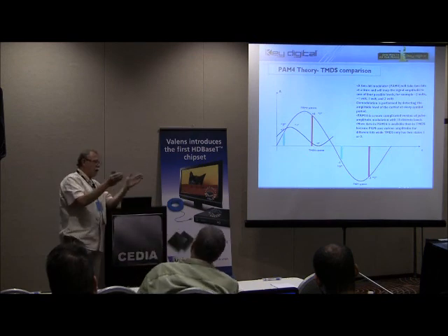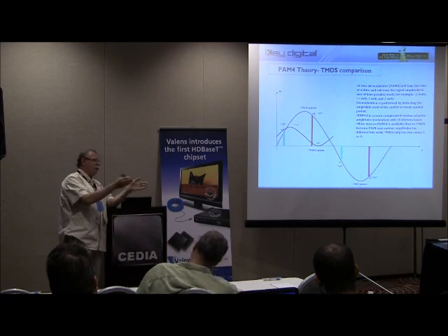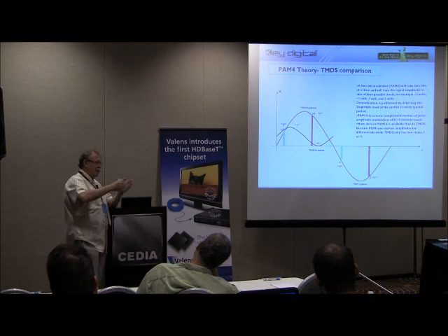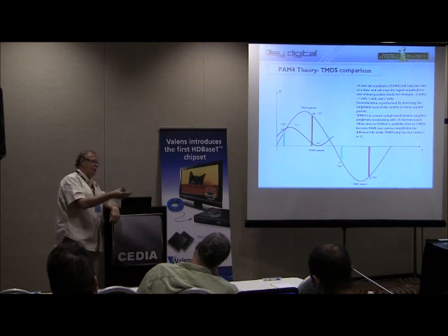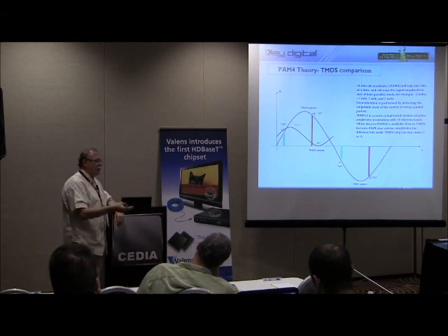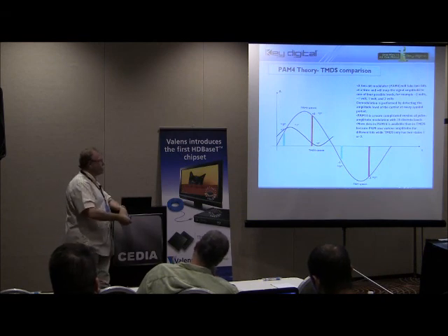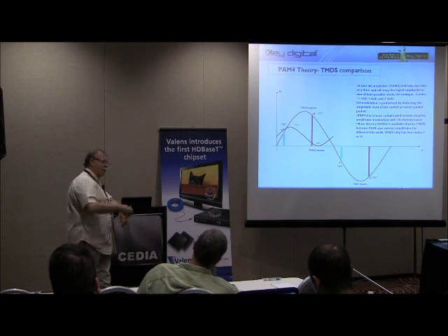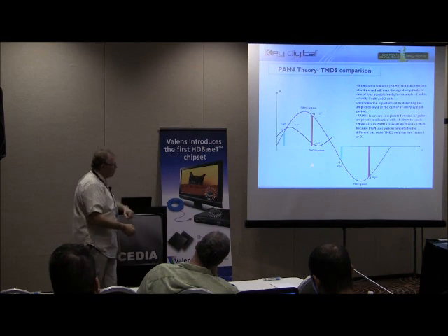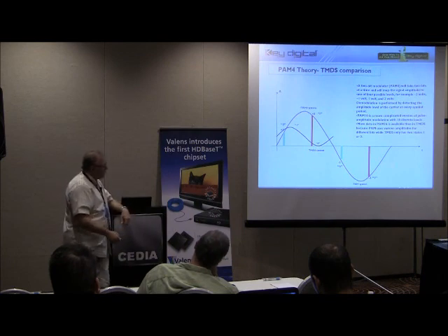And if you lower the clock speed, your jitter effects come into play later on, so you can send it over a longer distance. And since you have a vertical dimension for sending data over amplitude, you have more capacity, not only ones and zeros. You can send more data representation vertically in amplitude than with TMDS. So HDBaseT is a very innovative approach.